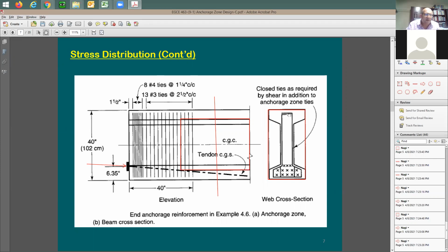And here is the design. It's going to look like this. It's going to be like a vertical tie. And of course, you need to anchor it, so I'm expecting that I'm going to have here some rebars. You cannot just leave it this way, right? This picture is just showing here the pre-stressing strands.